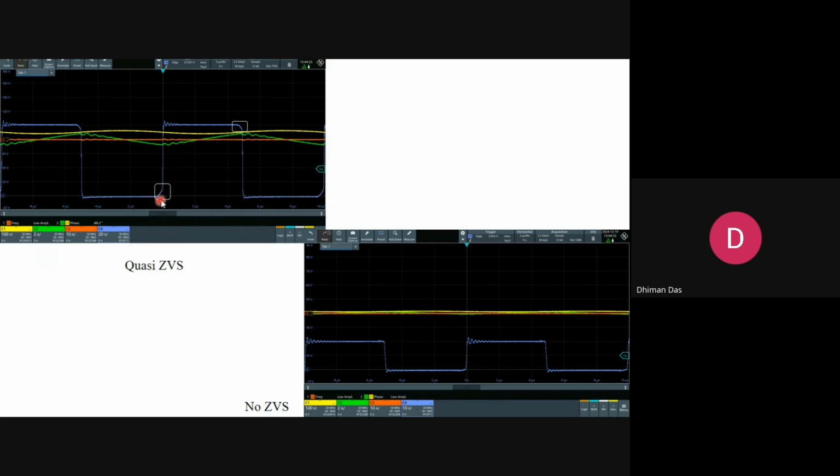Okay. Now you see, when I reduce the amount of magnetizing current, this slope. So see, this is only ZVS. This region is very small, but it rises up sharply. So this region is called the hard switching region. Yesterday I showed some plateau threshold. So this thing is just crossing those regions, and here is the region where switching loss happens.